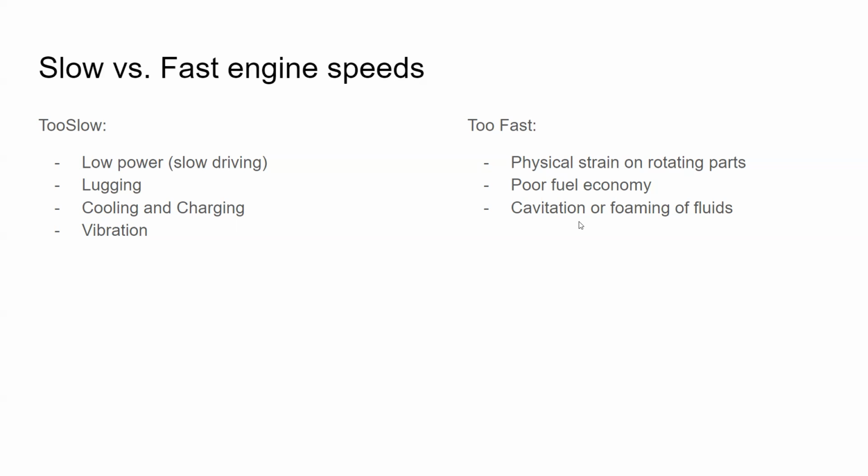You start revving it faster than that, say 4,000 or 5,000 RPM, and it might only last for a few minutes, like 15 to 20 minutes at 5,000 RPM before the cavitation of oil and coolant catch up to you and cause things to overheat or not get enough lubrication. And if you keep going beyond that, the problems become exponential.